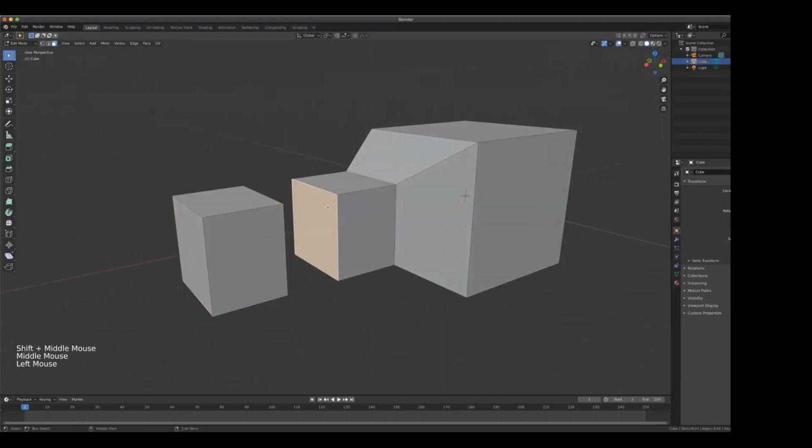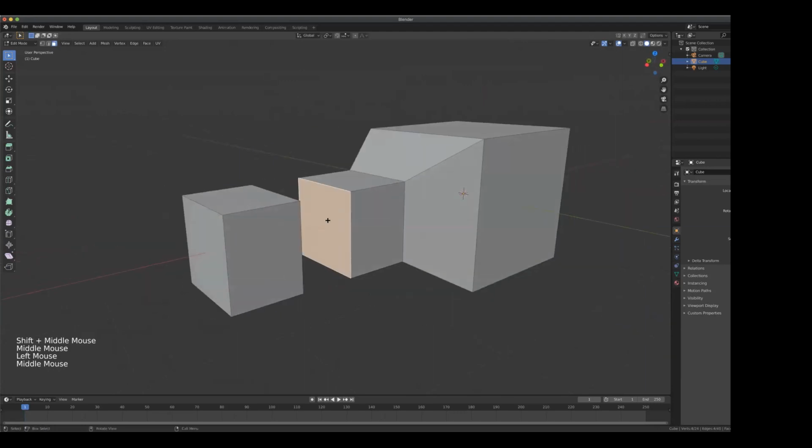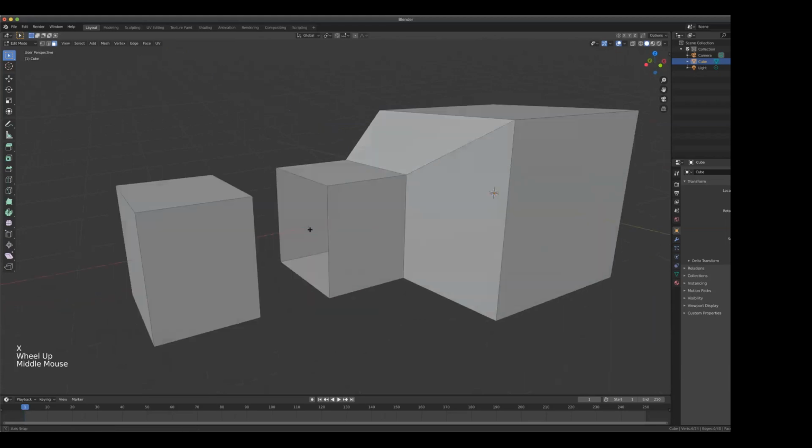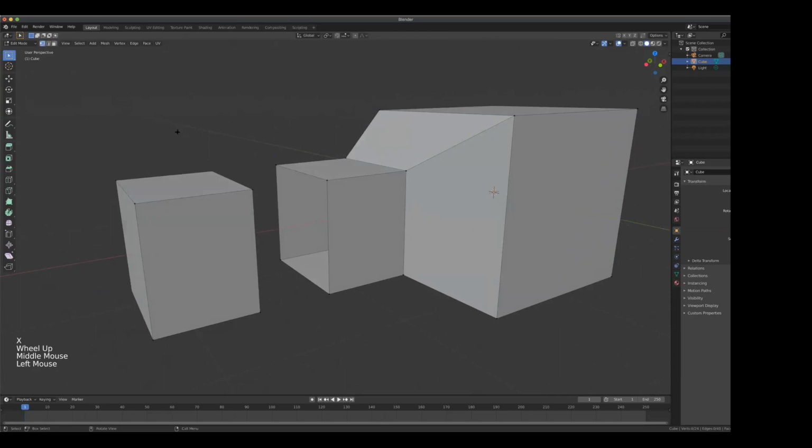First thing you need to do if you want to connect this, you can't have any polygon inside like this, because otherwise you'll have an embedded polygon. If you happen to add some modifiers to this later on, that will show as a mistake in a way, because you get some overlapping. So first thing, we've got to get rid of that one. Okay. All right, I'm going to go to point mode, or number one in edit mode.